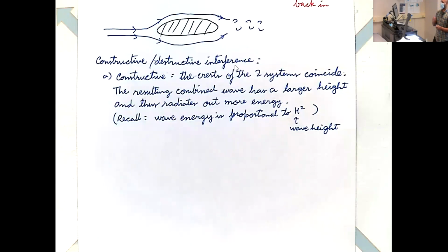What if you go slower and you have multiple waves along the hull? What happens to your drag? Is it constant throughout? Does it increase linearly? The surface area doesn't change, just the wave making drag changes. Does the wave making drag increase or decrease when you start going slower than hull speed? It does both, right? If you start going slower, you'll generate multiple waves. So at some point, you'll generate 2 full waves, which is nice, right?